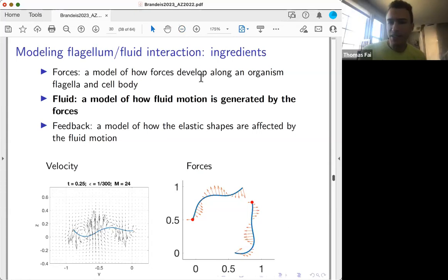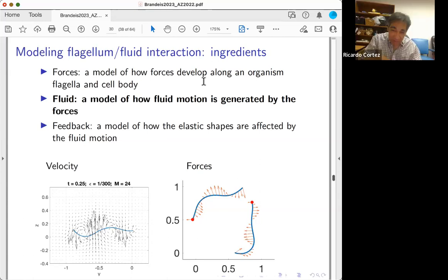And I guess I also had a somewhat related question. How are you implementing the tube? Do you need to compute a different Stokeslet in the confined case? Yeah, or we are putting a bunch of Stokeslets on the surface of the tube and solving that linear system that we talked about to make sure that the combination of all the velocities produced at the tube wall is zero.